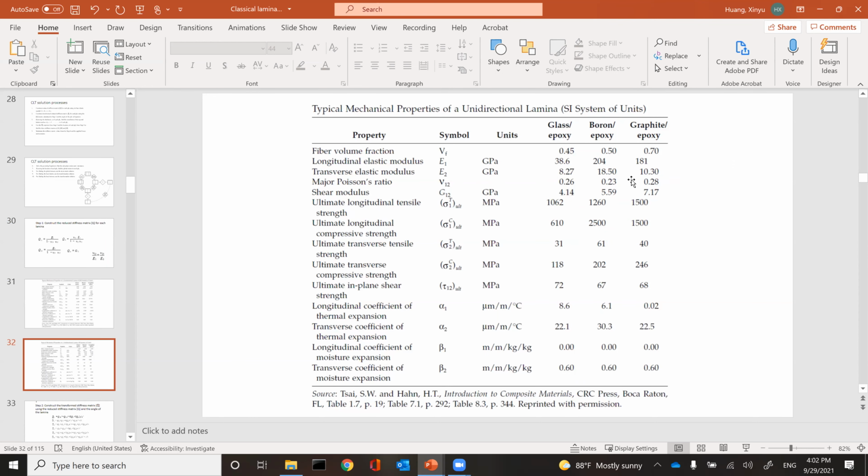So it depends on the units of the given conditions. You can choose English units, US customary units, or SI units, whichever is more convenient. If most dimensions are given in inches and pounds, I would choose PSI. If dimensions are given in millimeters and newtons, I would choose SI. It's just more convenient that way, right?